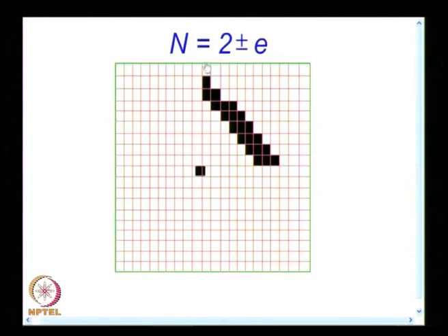And in this plot I have shown only one fringe order, and in fact you can develop the logical condition in a manner that in one shot it plots all the fringe patterns. That is the greatest advantage, and some of you who are good at computers, please go and develop the fringe contour for at least a circular disk under diametric compression. You can take it as a home exercise, and that will give you a feeling. Once you do it for one problem, you will feel like doing it for several problems, and you will get a visual appreciation of how the fringe contours look.